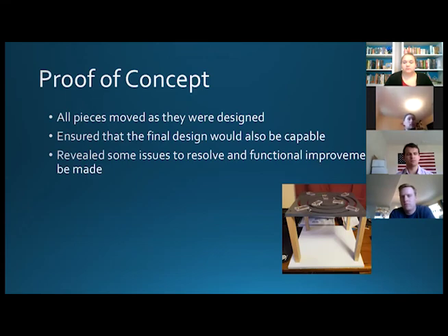To secure the rings concentrically so that they wouldn't interfere or slide laterally in their guides, we used stop gaps, little rectangular stop gaps that would fill the void in between the discs. Those proved to be a large issue because they would contact the hardware, the discs. They would make rotating the discs in the guides very choppy and not smooth.